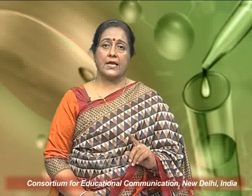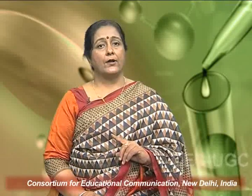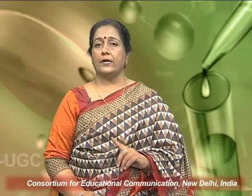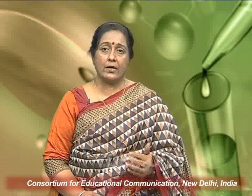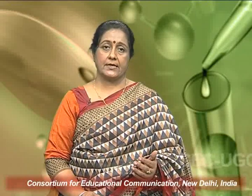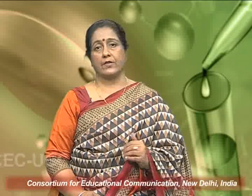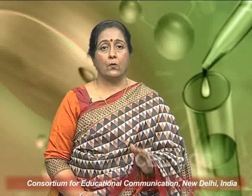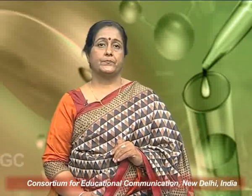It's because they have low viscosity temperature coefficient and are not readily oxidized up to about 200 degrees centigrade. They are, however, oxidized quickly above 200 degrees centigrade and undergo cracking at about 225 degrees centigrade. Silicones are very useful for low temperature lubrication of small parts.